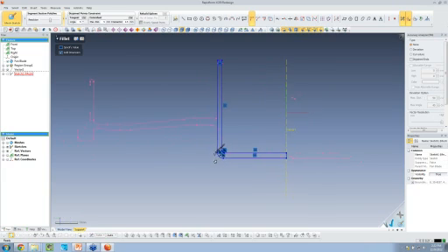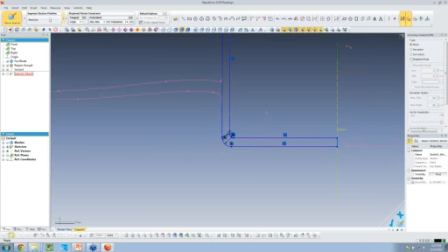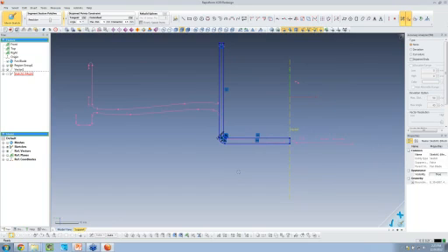And if you notice here, I actually have a numerical value that gave me an average, but I can also override my system at any time. It told me it was a 2.671392. So maybe, as an engineer, I should make this 2.5, just to ensure I don't have any discussions with my manufacturing department. Maybe this one I'd make as a whole. So I have the ability to also add my designer's intent as well, or I can just leave it as a verbatim model.